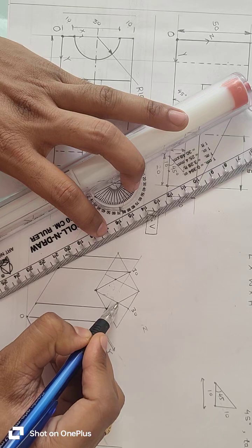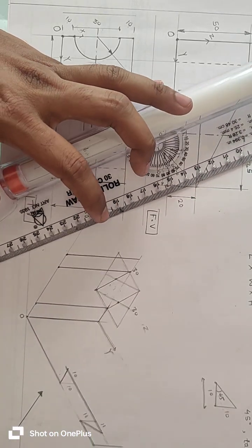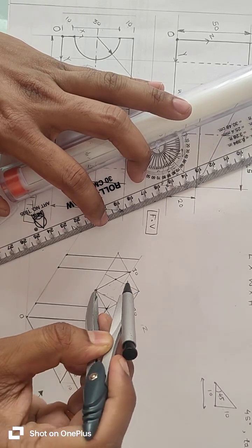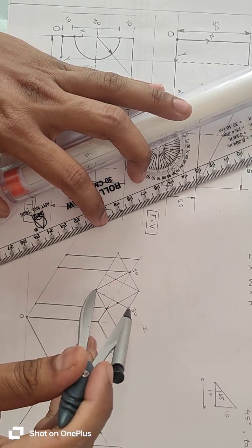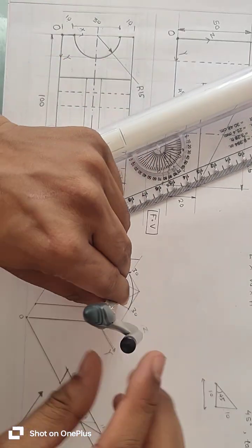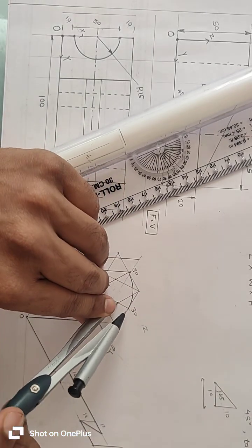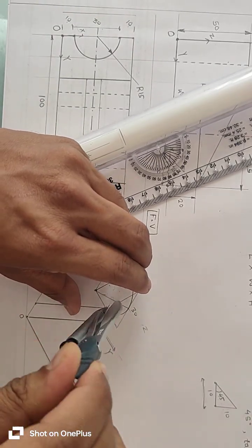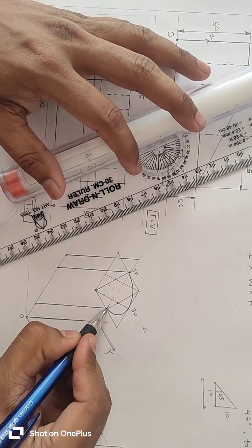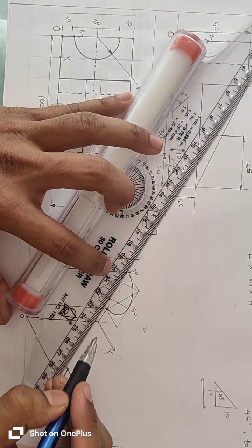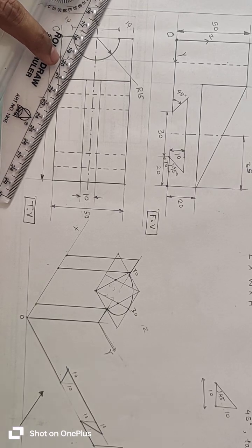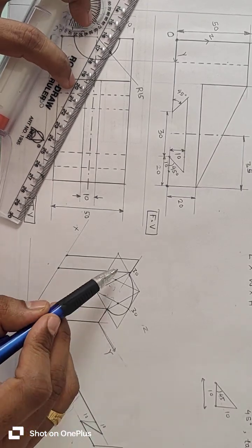These are the intersecting points. To draw this semicircle, we need this center point and this as a radius, an arc between midpoint and midpoint, and then this as a center and radius equal to this, midpoint to midpoint, this is the smaller arc. So this is our required semicircle. There is no need to draw a semicircle here.